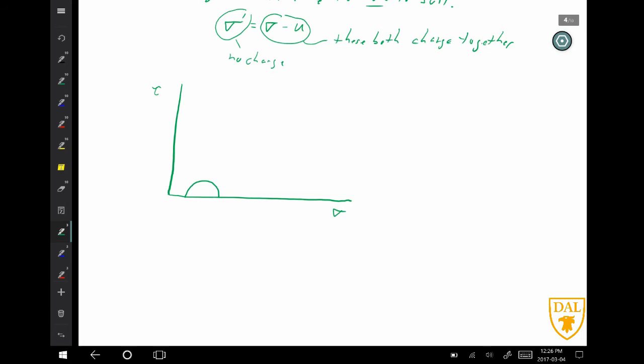Now, if you increase the confining stresses around your specimen and you do the test again, like I said, all the stresses go to the water and none of the stresses go to the soil. So the soil is completely unaffected and essentially has the exact same strength and fails in the exact same way at the same shear stress.